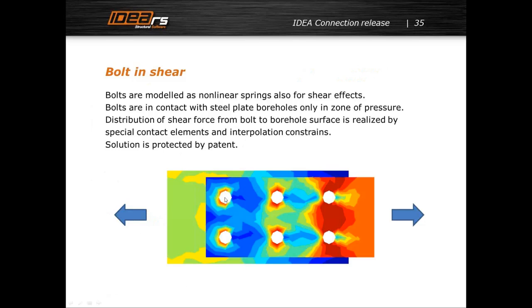And what we do here is that we have a special model which can transfer the shear force from the theoretical point of the bolt to the edge of the borehole, and we use again some contact elements here, and you see that the force is really put only on the part where the bolt is pressing into the material of the plate.